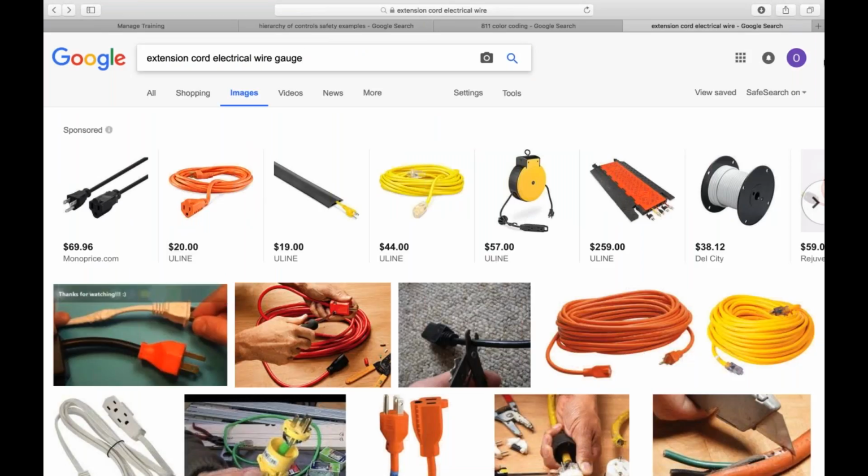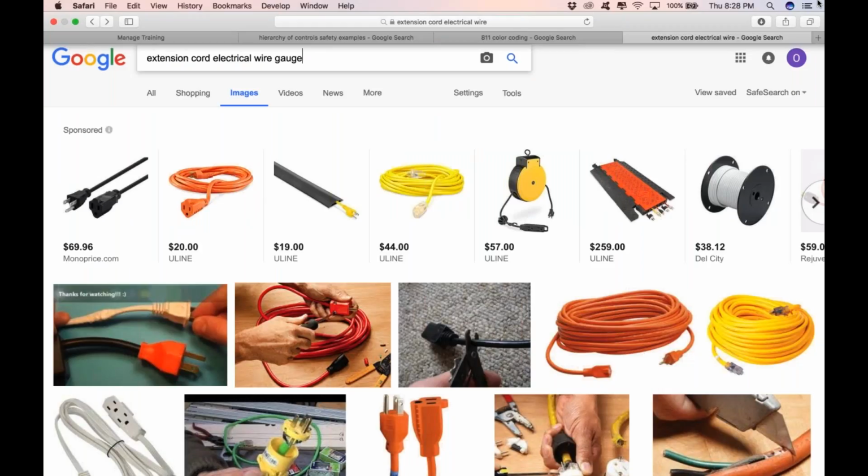Okay, so extension cords, and then air movers or any type of gas freeing equipment as well, right? Ventilation equipment basically is what we're talking about: fans, extraction fans, air movers, items like that. And then work permits required.